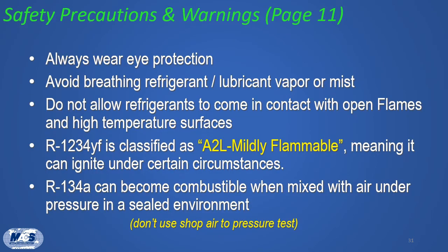And one of the most important safety comments I can make is to always, always, always wear your eye protection. When refrigerant's venting out of a leaking system, it can come out at close to negative 50 degrees Fahrenheit, which is cold enough to instantly freeze your eyeballs. So please always wear your eye protection and do not take a chance.